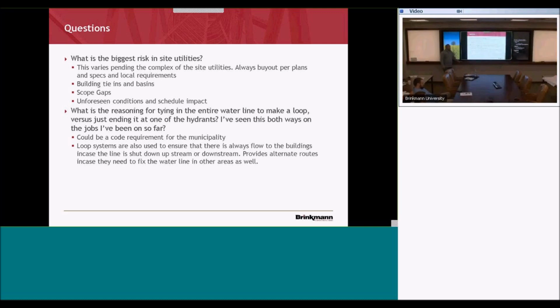If you need to locate a utility, we've had a couple situations where we had utilities that we kind of thought we knew where they were. Those vac trucks use pressurized water, and they vacuum out the water, and it's the safest way to excavate around utilities. They're not really expensive to get. They're pretty slick, and that's what a lot of people are referencing as potholing.